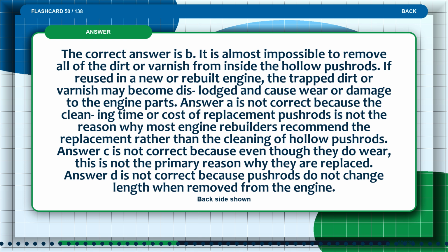Answer A is not correct because the cleaning time or cost of replacement pushrods is not the reason why most engine rebuilders recommend the replacement rather than the cleaning of hollow pushrods. Answer C is not correct because even though they do wear, this is not the primary reason why they are replaced. Answer D is not correct because pushrods do not change length when removed from the engine.